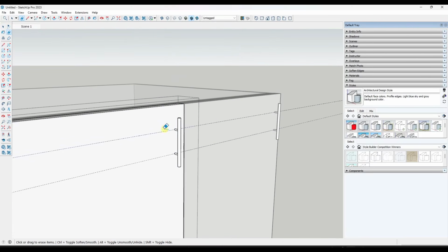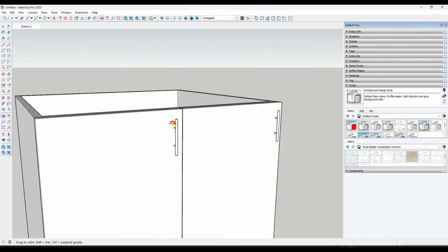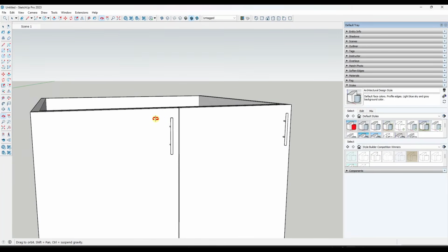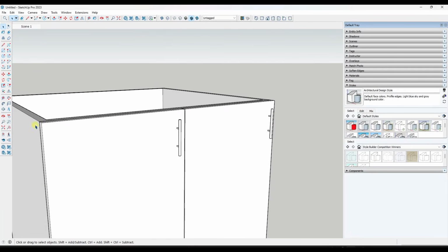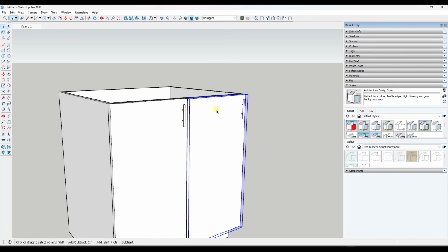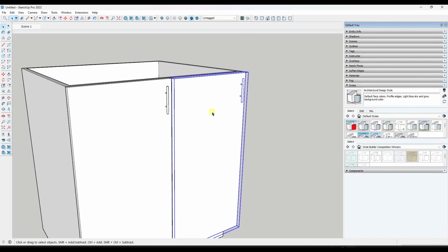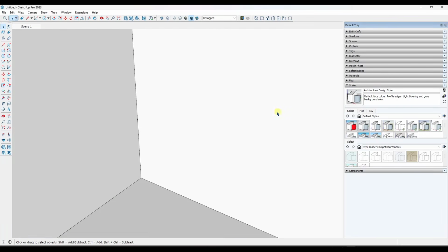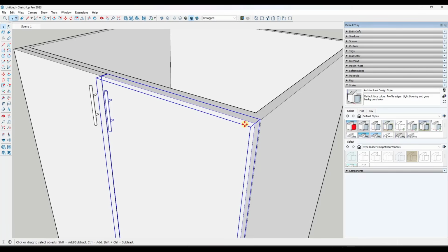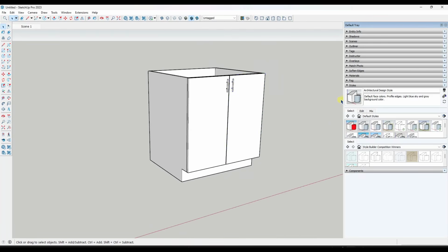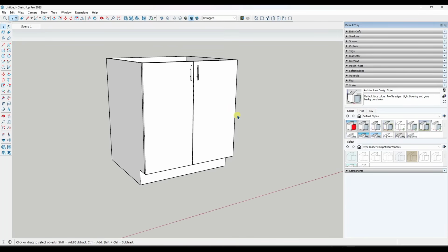And so then within this group, you can erase out the guides. And so this is what I wanted you to see: we've got our pulls in here, but notice how, because of the way we copied this across, this pull is on this side of this object. What I would probably do in this situation is use the flip tool in SketchUp 2023 and just flip this in place like this. And then I would take this corner and align it with the end right here.